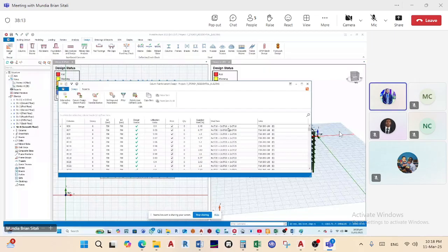So let's see, what is this saying? Saying the utilization ratio is 0.29. So with this utilization ratio, if we distribute this column over everything, what is the maximum utilization ratio that we will have? We use the same settings on all the other columns. Here, then paste. Then we'll find that the maximum utilization ratio now looks like it's 0.36.